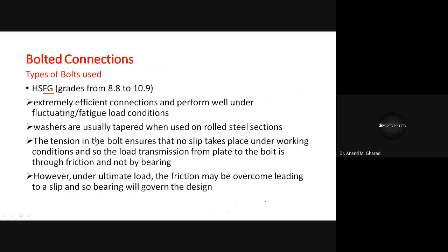Right. So this chance is very rare in case of high strength friction grip bolt, because the maximum capacity is taken care of by that friction action. The load transfer mechanism is through friction and not through bearing. But sometimes there may be a case that under ultimate load, the friction may be overcome, leading to slip, and so bearing will govern the design. Right? So there are chances.